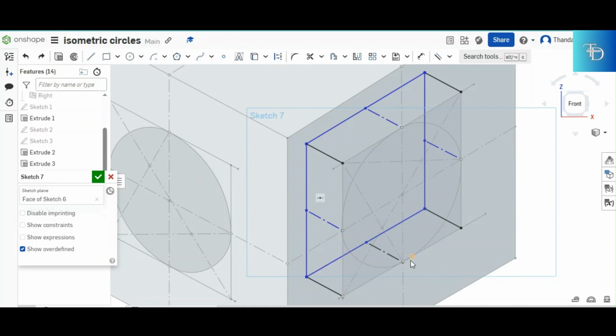Now, the next thing that you do after transferring your centers, you join what? You join the 2 points that have the longest distance apart, which in this case is this point and that point right there. And in the next step, you construct a V from that point down there. And you already know where your V should go. If you construct it from there, it should go and touch that center, and then it should go over and touch this center also. We go over and do that. Your V touches that center and that center also.